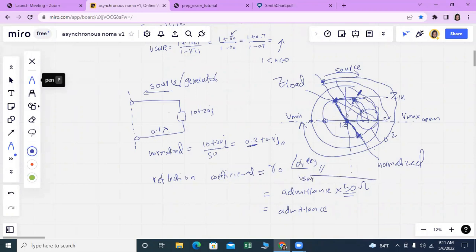You can keep one end of the compass at the center of the VSWR scale, and the other end at the length that you measured here, and then you can find the corresponding VSWR value.